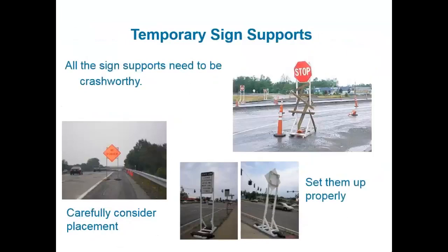Temporary sign supports. Everyone chuckles at that. That is not the way to do it. Placement. If you can, get them off the shoulder a little bit more or on the other side of the barrier if possible. Set them up properly. This one doesn't look too awful. It's kind of close. This one has a pretty good tilt to try and straighten that up a little bit.